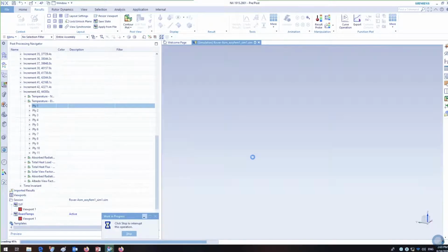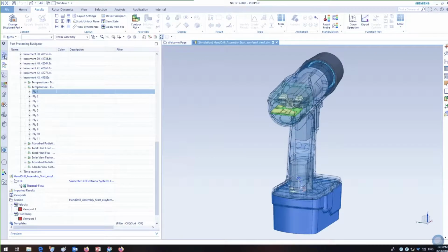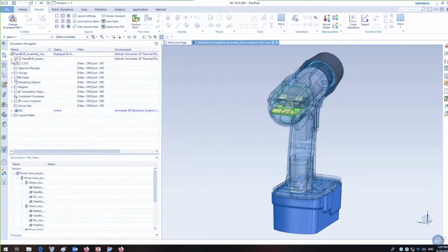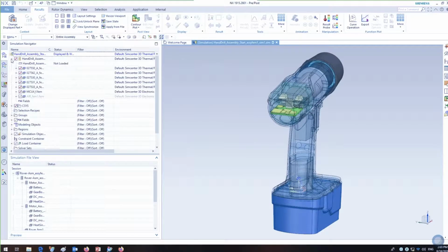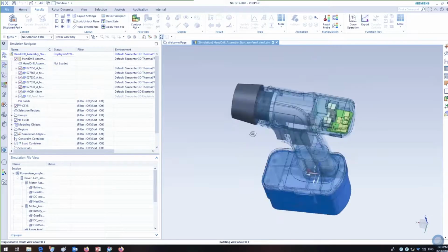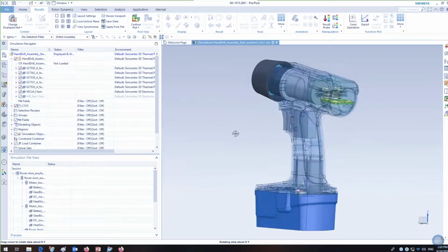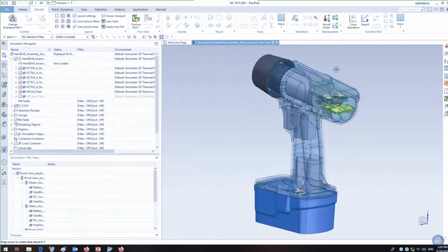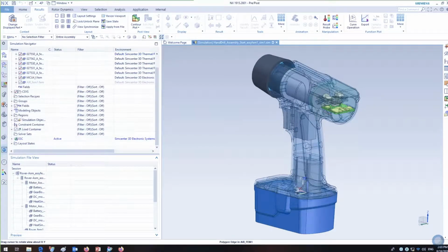So in an analysis where this board was, for example, used on the space station where there is an atmosphere, or on Earth, we can also reuse the PCB thermal model the same way we did it for the rover model using the assembly FEM method, but by adding air inside.